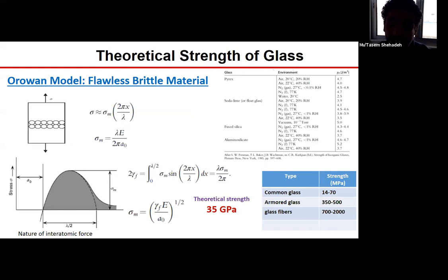So if we imagine that we have a piece of fiberglass that is defect-free, it is manufactured such that the surface has zero defects in it, zero cracks in it. And we pull this sample in tension, as shown in this figure. One can prove that the stress required to fracture the sample is related to the surface energy. When the sample fractures, the mechanical work that is done on it is transferred to form two fractured surfaces.